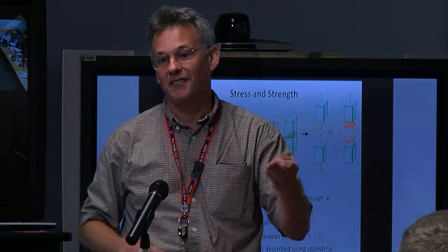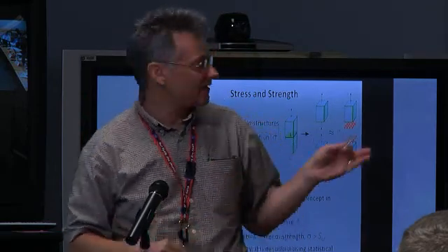Well, that's when you get to strength. Strength is now a material property. That's the bottom bullet there. It's another basic concept in structures. And so stress, you can put as much stress as you want on something, but eventually it'll break. And that's the strength. The strength of a structure, strength of a material, is the stress that causes failure. And failure occurs whenever the stress is greater than the strength. So you pull on something until it's past its strength, the material property that says this will break, and then it breaks. But it's not an exact property.